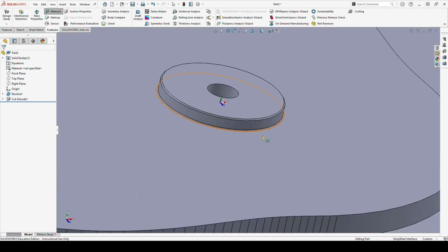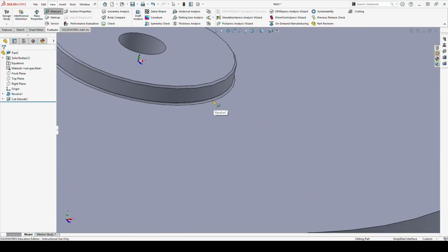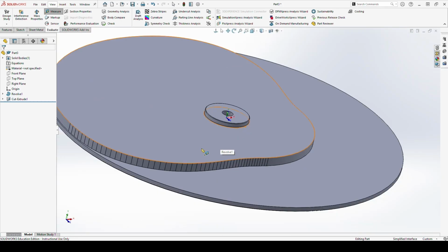And then if I look in here, I have a chamfer right along this edge right here. So going through, let's see if I can't draw that a little bit better. Going through, I've got a line, I've got a chamfer right here, and then I've got my fillet, my curve right here. I've set these to be very small. If you recall, I set them both to be 0.1. So I went ahead and you can look at that, and that is 0.1, even though I didn't quite get the measurement on right there. Wasn't quite acting up correctly for me there.